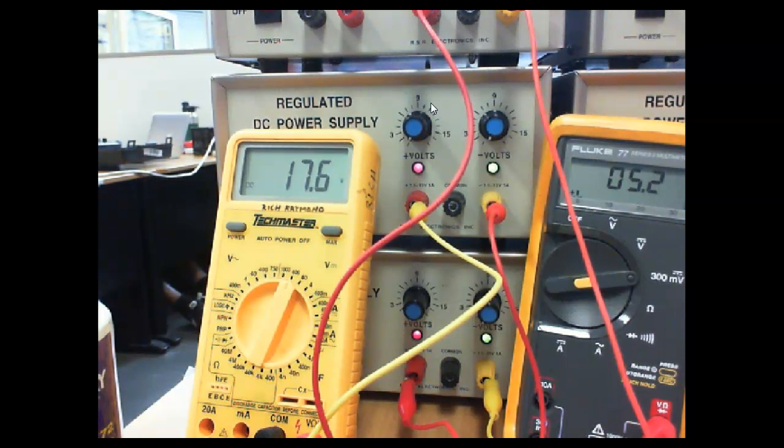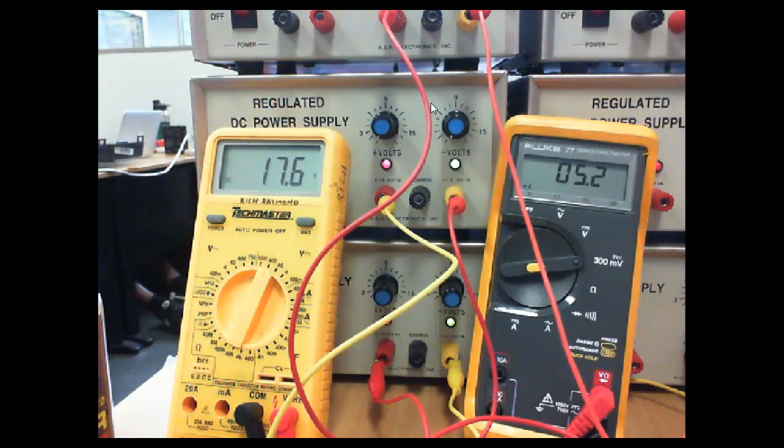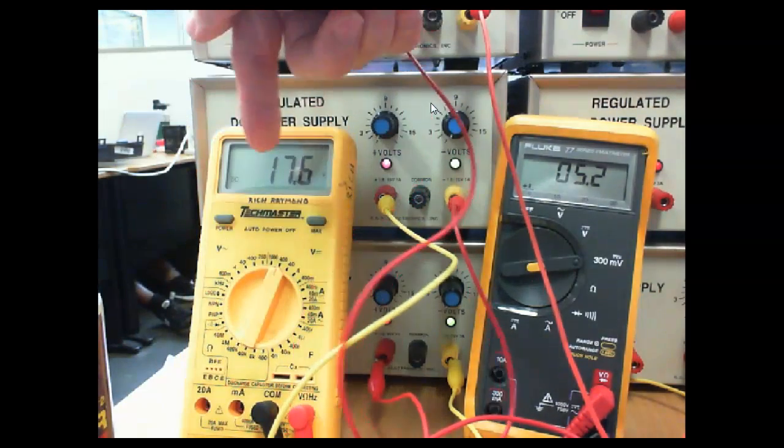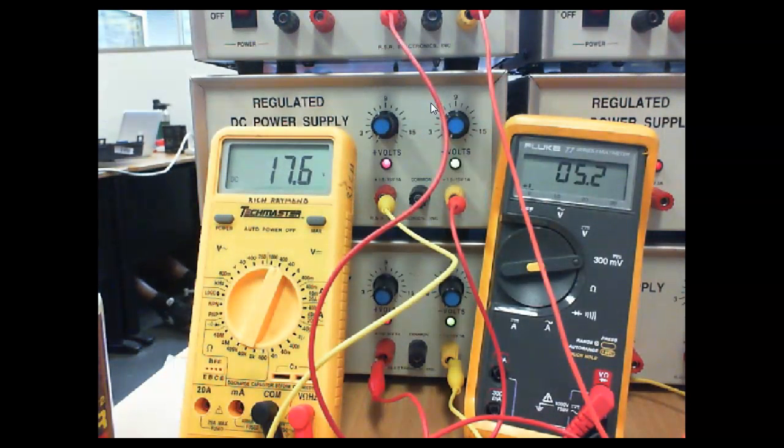The one on the right is on millivolts, by the way. So this is 5.2 millivolts that we're looking at right there. This is on the 400 volt scale. So this guy right here is measuring volts. This is millivolts. So right now we're looking at a leakage current. We would say 5.2 milli divided by 1 mega ohm, and that would give us the current. So what leakage current do we have right now? We're not going to record this.